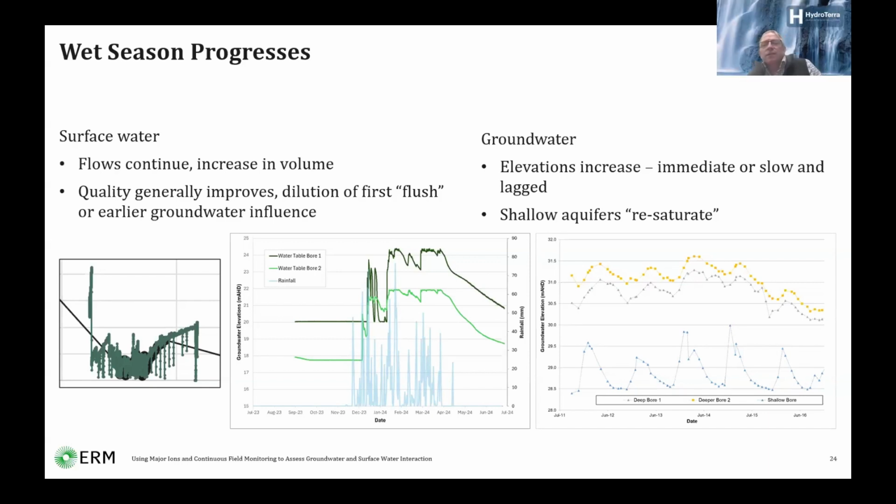Dana, one thing that I've observed, well, I did my master's on it, was we were looking at near stream shallow groundwater responses, and we found that antecedent moisture conditions was a key determinant in observed groundwater fluctuations. So near stream sort of flatter areas which were close to saturation but not, they would rebound really, really quickly in response to a rainfall event.